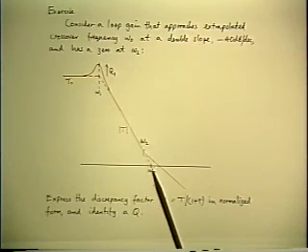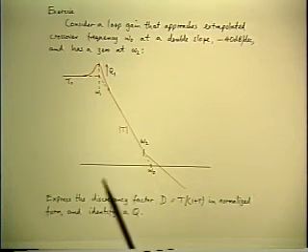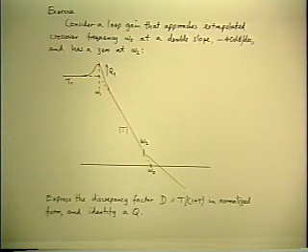Write the factored pole zero form for T, plug it into the expression for D, which is T over 1 plus T, and see what happens to D. See what its shape is, factored pole zero form. See if it has a quadratic. If so, what is it that determines its Q? So it's a parallel problem to the one we've just done. So look at that for a few minutes, and mainly just to the point of setting up the problem, which is writing the expression for the factored pole zero form for T.